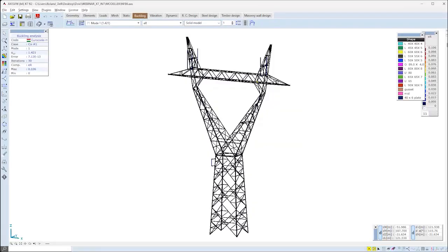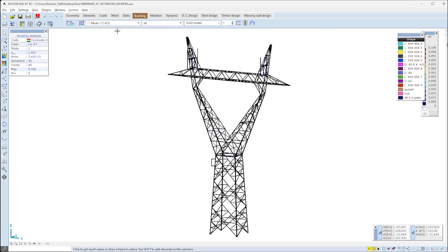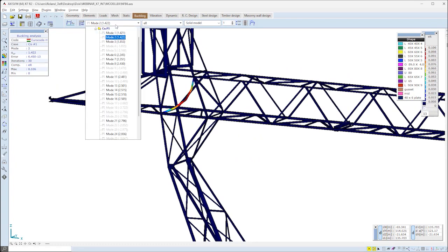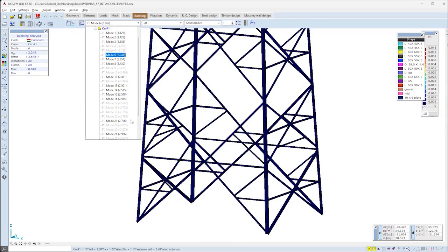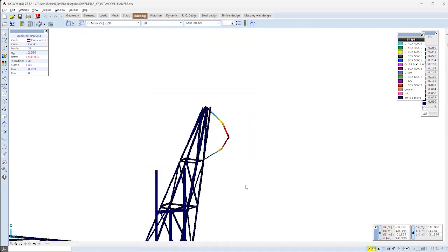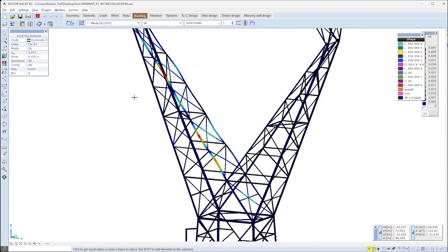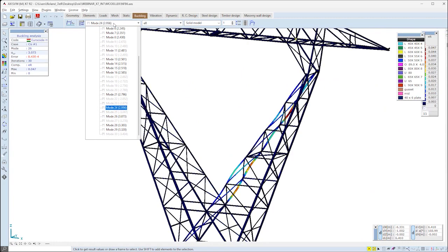The results of the buckling analysis are the buckling mode shapes and the eigenvalues. In the first drop-down menu, the 30 calculated shapes are listed. Checking the first shapes, it seems that they are local buckling shapes of trusses. They are scattered all around the structure and fill up most of the calculated mode shapes. Global buckling shapes start to appear from the 20th calculated buckling eigenvalue, relatively late in the list.